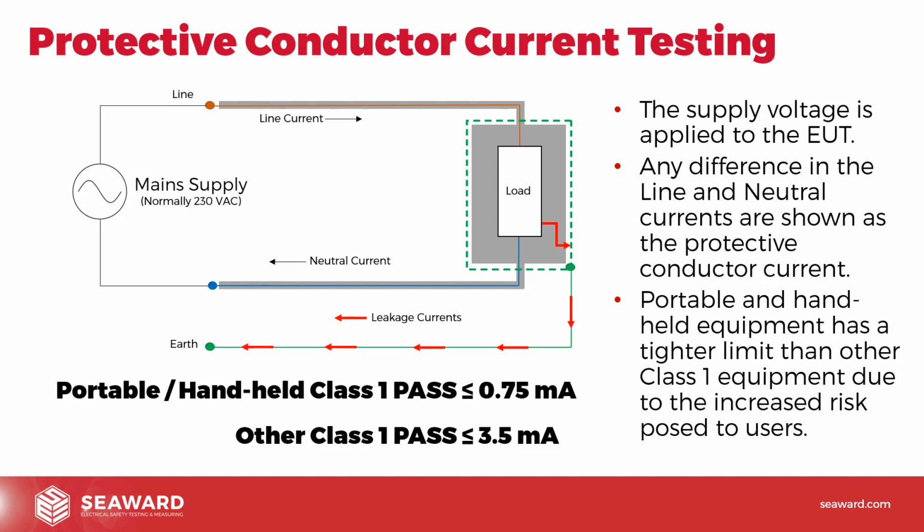And this is quite often where people get themselves into problems, particularly with manual tests, like the Prime tests, where the pass-fail leakage limit on the Prime test 100 is set to 0.75 milliamps because you can't change the test sequences. So we've set it to the safest limit possible. We've set it to the safest limit on there, which is 0.75 milliamps.